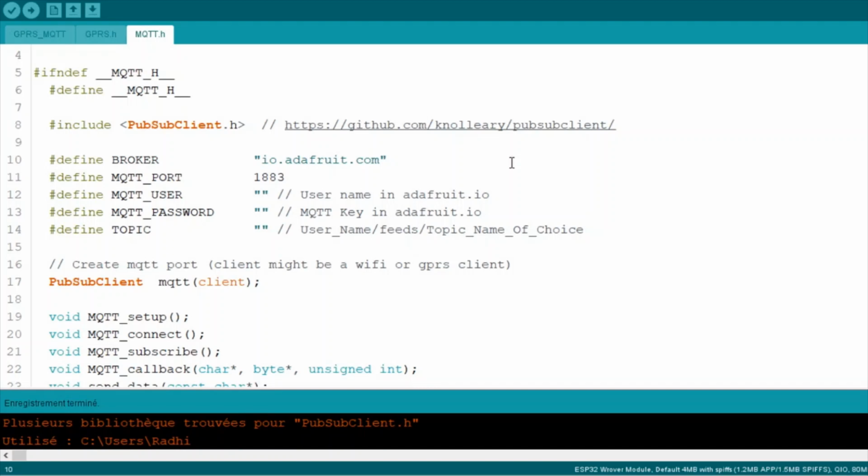You put two topics, one for temperature and one for humidity. What does the broker do? Your ESP has published to the MQTT topic called temperature. It associates that data with that specific topic. When my phone, let's say, subscribes to the temperature topic, it gives it that data.